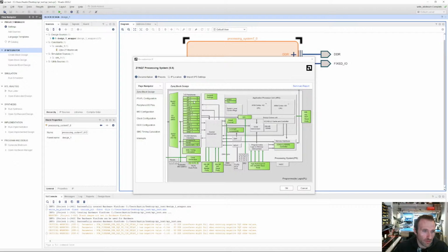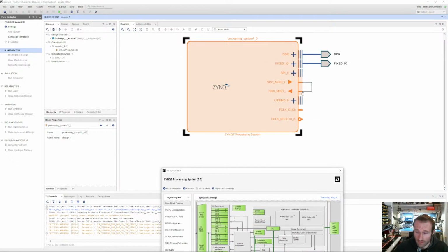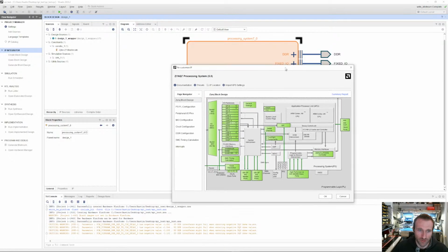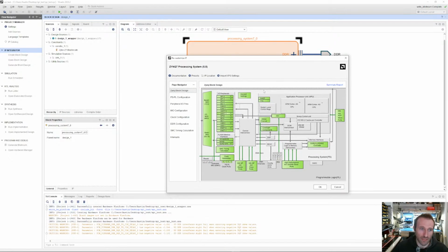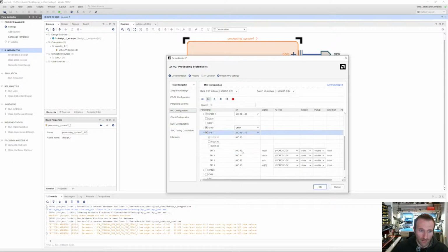So as you know, SPI 0 is loopback right here. I do that internal to the FPGA. It's not actually going out of the board anywhere. So that's kind of slick for loopback testing for SPI. There's a second channel, and that second channel is going to the connectors. The right question is, where on the connectors is it going?